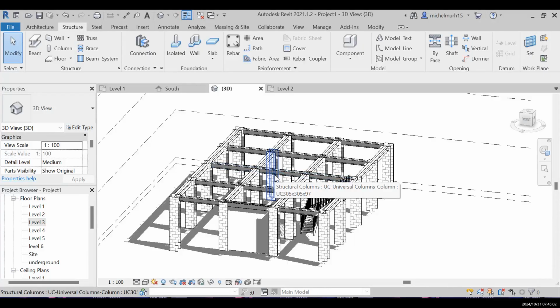So to complete the remaining floors here, I can just copy the first floor to the second floor, but it's not professional, because maybe the first floor and the second floor have different heights, right? So I have to adjust the columns again. In this case, I'm going to repeat the same process that I did for the first floor. For each intersection in my grid, I'm going to add a column and a beam, okay?